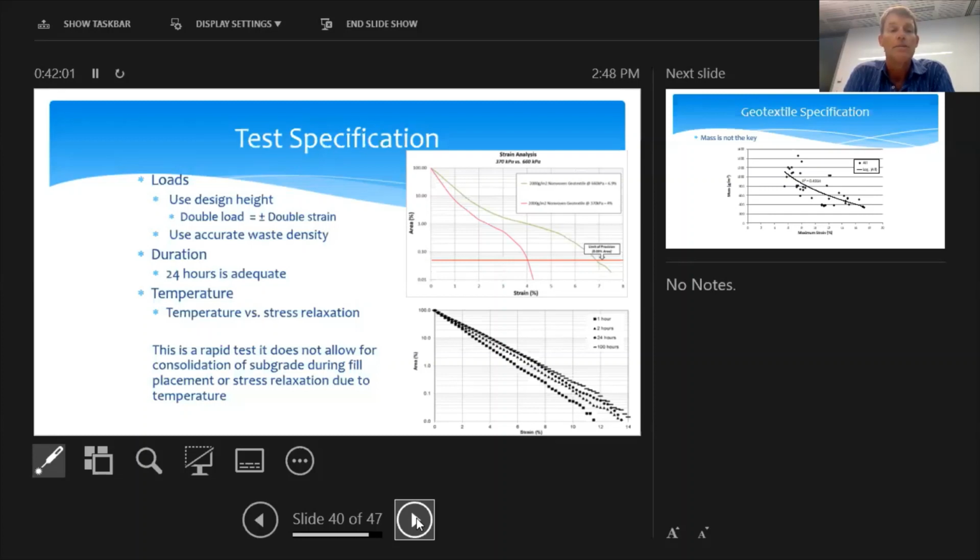The UK standard requires extra load factors to allow for temperature, but it doesn't allow for stress relaxation. And I think that as a designer, you should take into account that over time, HDPEs will stress relax, and you need to be aware of that. If you only allow for temperature and not for stress relaxation, you're over-designing your materials.